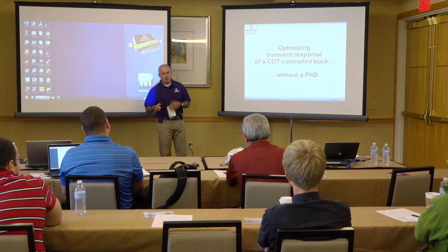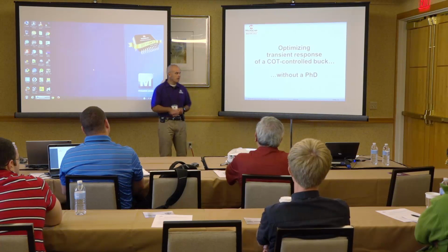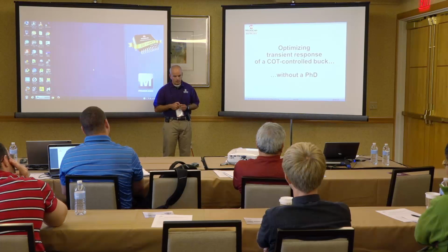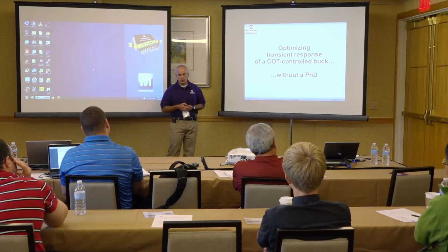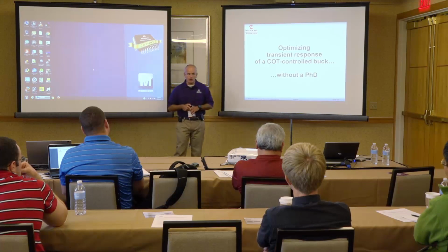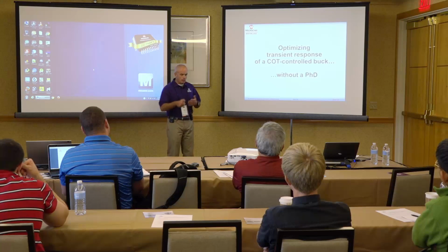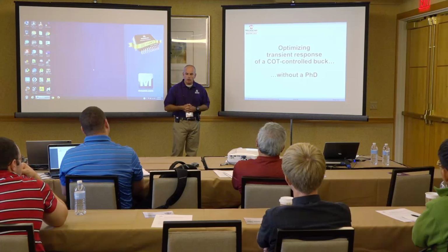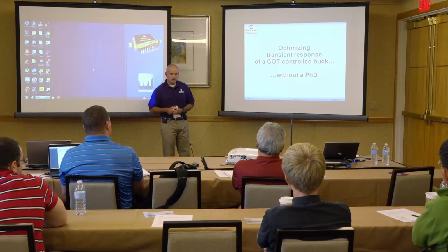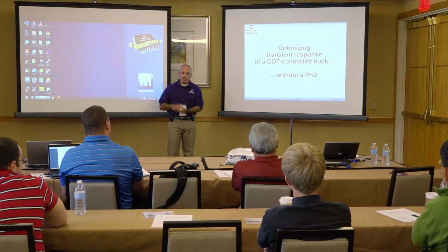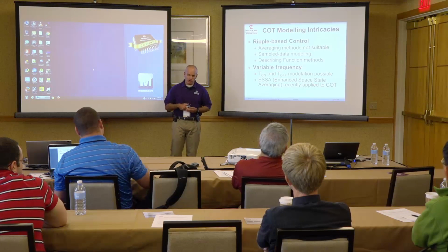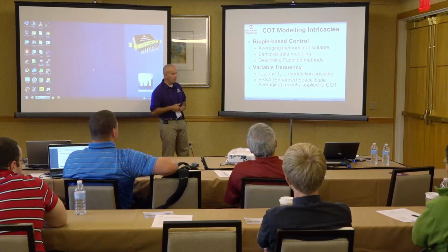So that's the case where we have to add these two components actually, and one is a fixed 0.1 microfarad capacitor, the DC blocking capacitor that Surya mentioned. Well, we are adding a couple of more components, so maybe there is some room to optimize things. Unfortunately, optimization requires modeling homework, heavy modeling homework.